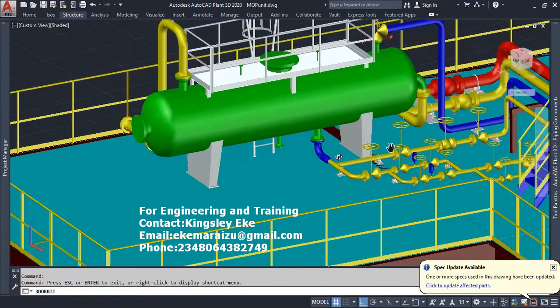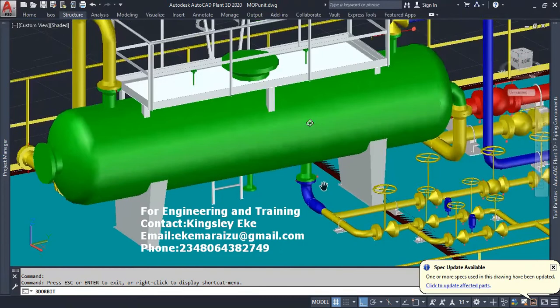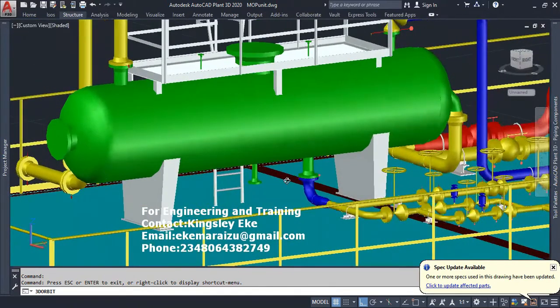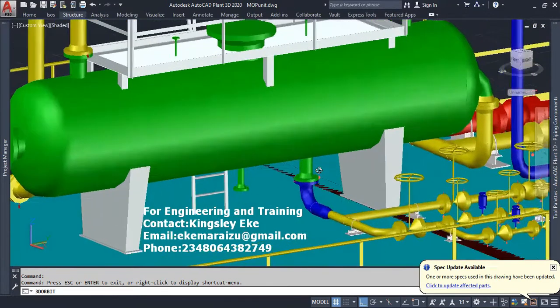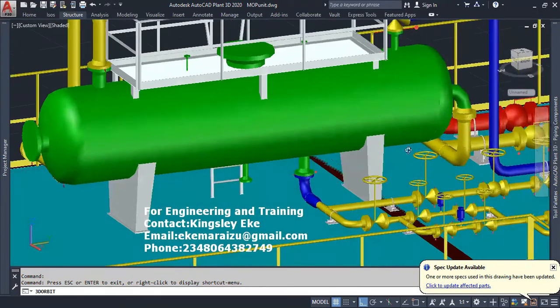So whether it's a low pressure crude or a high pressure one, separation occurs. A separator separates gas from the liquid line. So if it's a two-phase separator, it separates gas and liquid. The gas is routed in this place, while the liquid comes here.